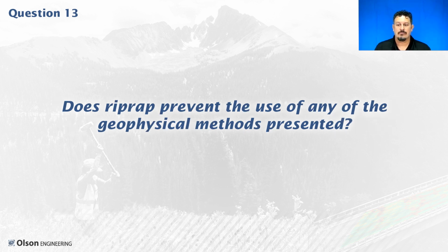Does riprap prevent the use of any of the geophysical methods presented? Yeah, so riprap makes doing resistivity tomography or any of the seismic surface surveys really difficult, because you have to be able to couple either your electrodes or your geophones to the medium, and the riprap is typically a giant rock.